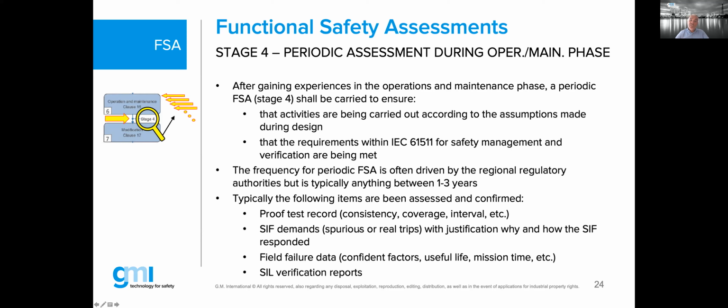We also want to see the spurious trip or the real trips. If you did have a trip on a safety loop, we want to see the root cause analysis. Why did this trip occur? What was the reason? We want to see this documented.